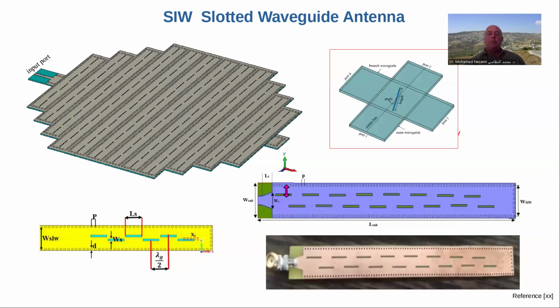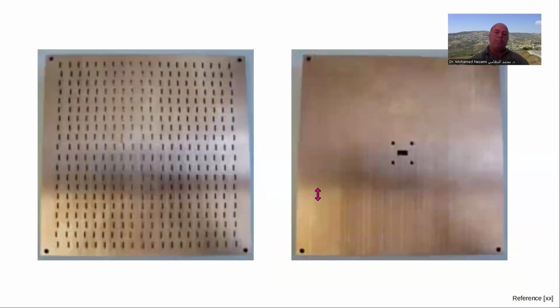And then you can also construct the aperture like this, where the input comes in here, and you've got inclined slots in the back that will leak the RF, feeding the RF to the center of every one of these waveguides that are placed. And this is very simple to construct. There are some publications on this if you would like to refer further to it.